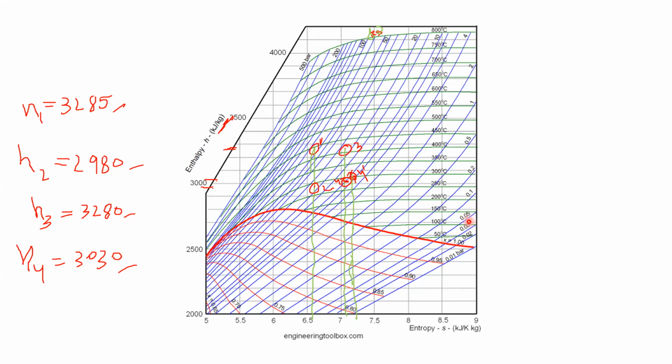If you look into this Mollier diagram, this is the 0.05 bar line and this is the 0.1 bar pressure line. At this position, we have the 0.07 bar line. If you extend this line up to this constant entropy process line, at this position, I have the fifth state.